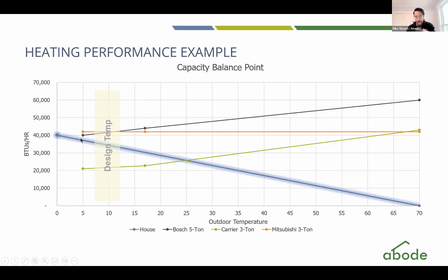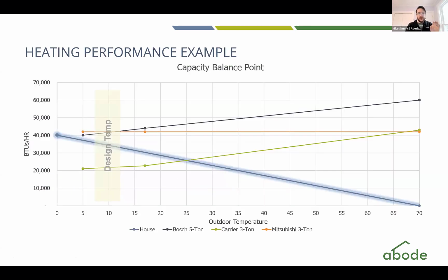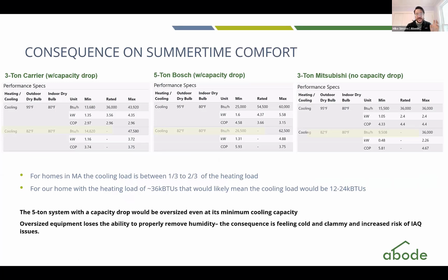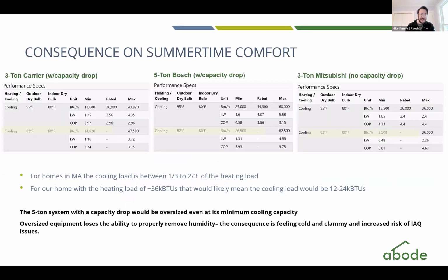We're not going to talk about polar vortexes right now. We're just going to focus in on that design temperature and what each of those heat pumps does. So I want to highlight this as why that Bosch system is not a great setup.